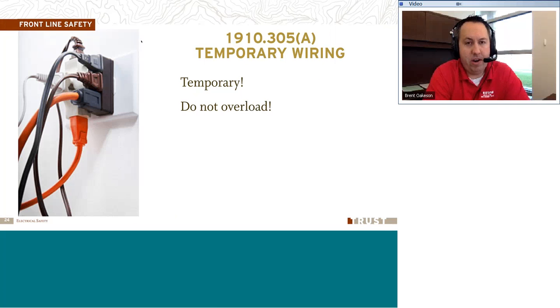As far as temporary wiring goes, a lot of people use extension cords in office spaces, in workshops, and on construction jobs. There are lots of different uses for those cords, but the key word here is temporary. These are intended for temporary use. They're not to be used for a long-term situation, like running equipment for a long time or running circuits. They're not a dedicated circuit. These are just a temporary electrical cord that you can use to run temporary power. So don't overload those things. Always make sure that you're using them with the right sizing, the right type for the work that you're doing, and make sure it matches the things that you have going on there. Remember that they are temporary.